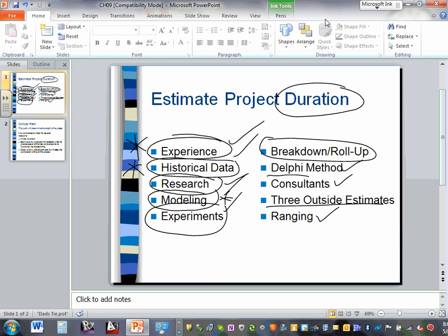But for network analysis, there are two terms that they use. One is called CPM versus PERT. PERT stands for Program Evaluation and Review Technique, and CPM is the critical path method, what you're looking at right here. With PERT, they assign a probability value for each activity, and they come up with a duration based on the possibilities and probabilities. I'm going to spare you guys the analysis on that one.